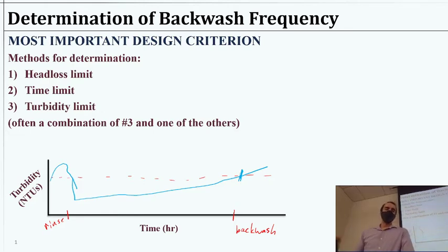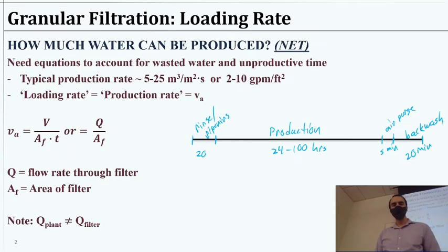So something like that would happen for our turbidity, because in the rinsing step, we've got lots of particles that were dislodged and now are freely floating around, and we need the sand grains themselves to settle in order to have a chance at capturing things. So that rinsing step or priming step is really important, and you can see very clearly if this is what's happening, that's why we're not going to use water being produced in the first few minutes of operation.